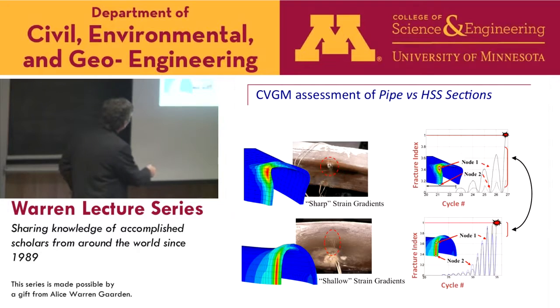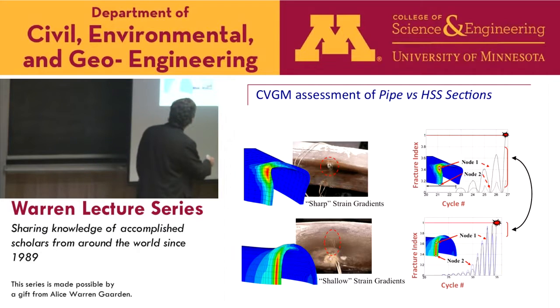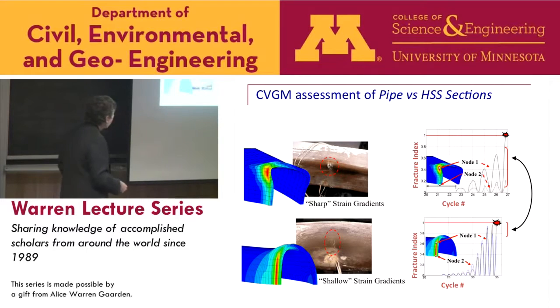So the plots on the right are for 2 different specimens, the square tube and a round tube, different cycles, and the screen didn't come through real clear, but we're looking at kind of 2 locations on these to monitor the void growth index. And of course, we'll pick the one where it's highest, and then the red lines shown here would be the value that we calculated from our model, calibrated to the material tests, when we would predict these braces would fracture. And we got generally good agreement.